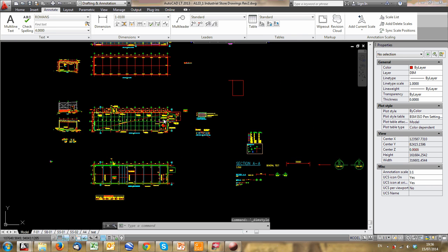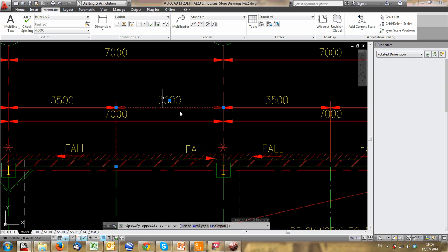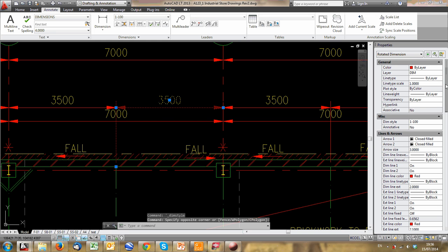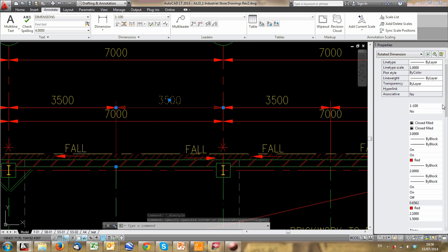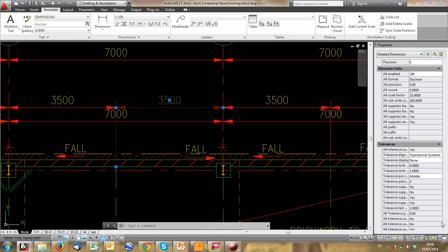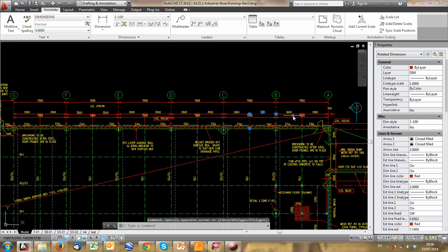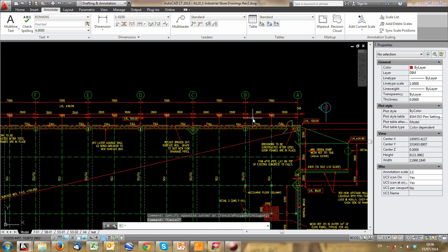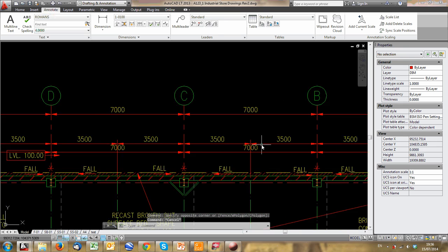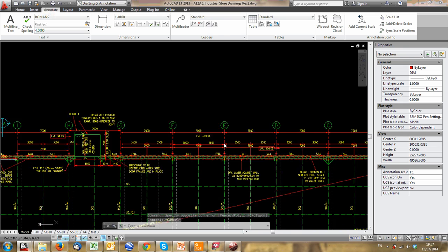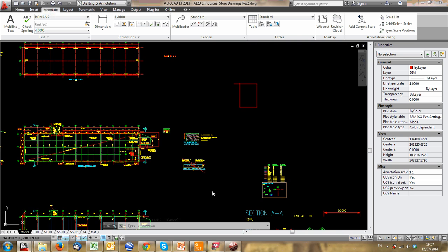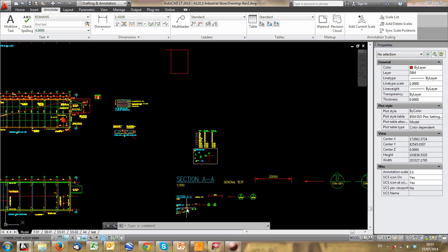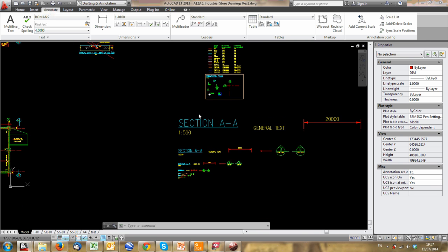If, however, you've drawn something, you can even edit just one at a time. You go to it, go through the properties, and start editing your dimension styles. But normally the easiest thing is to set up a set of dimension styles and then use it repeatedly for all your drawings. It makes life much quicker because you know exactly what you're drawing, all the details, all the dimensions. It's all there right in front of you, and it also matches what you've got set up here.